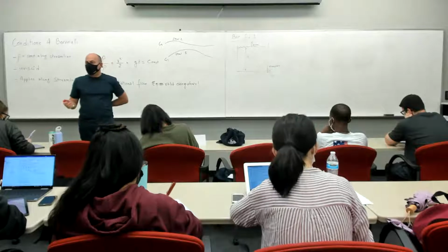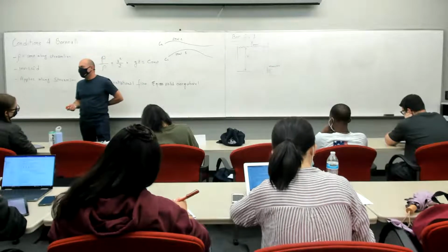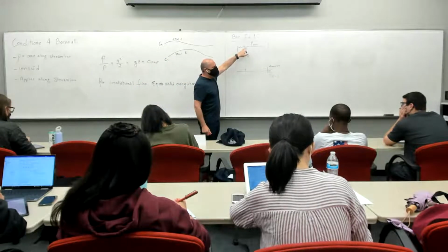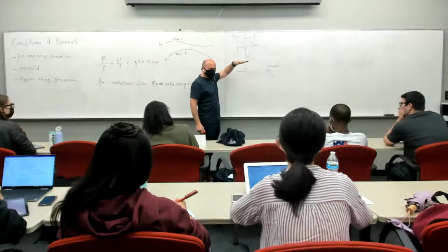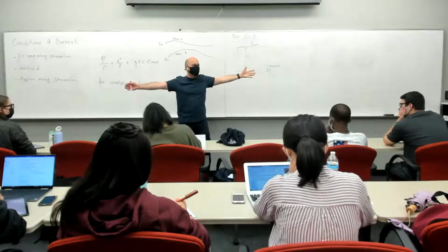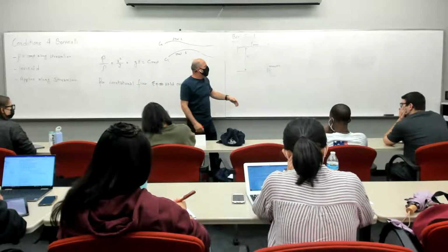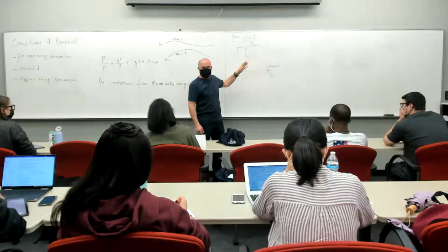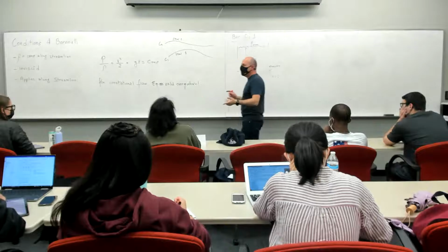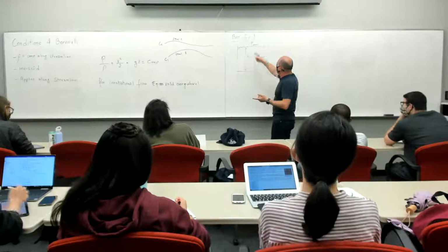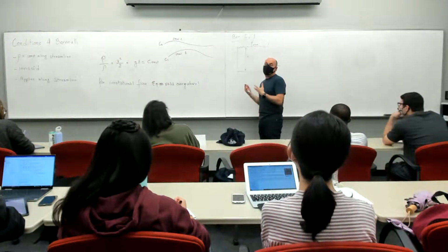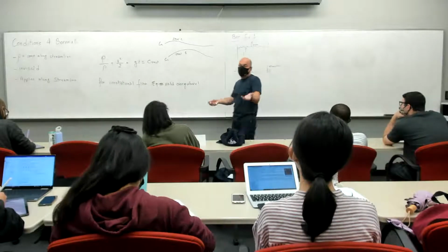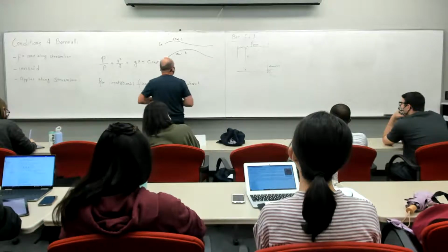Now you ask yourself, does mass conservation help us in this case? Doesn't really, because over here there's barely any velocity. The flow is going down very slowly. This is a huge reservoir, right? Mass conservation might help you with H a little bit, but it will only give you a relation between the V exit and the V inlet, maybe. So you really need momentum over here to extract the velocity out. And momentum is essentially Bernoulli as far as we know now.